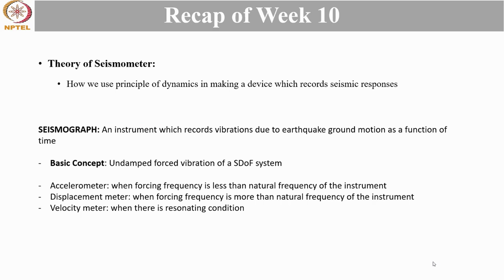And then we learned about seismometers. A seismometer is a device that puts the theory of structural dynamics into practical application for recording responses of earthquake vibration. These are based on the basic concepts of undamped forced vibration in a single degree of freedom system, and through a complex solution to the system, we saw how a seismograph can act as different response recording devices. When the forcing frequency is smaller than the natural frequency, a seismograph works as an acceleration response recording device, also known as an accelerometer.